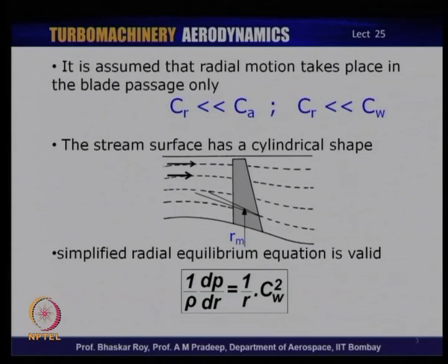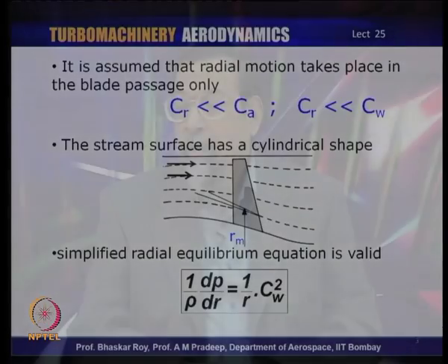So, that one can say that it is very small compared to the axial and the lateral or the whirl component of the flow. Now, this is something which the designers often would like to do by design at the time of designing of the axial flow turbines. If you can do that properly, when the turbine is actually operating, it would more or less stay very close to this design assumption or what has been invoked by design.